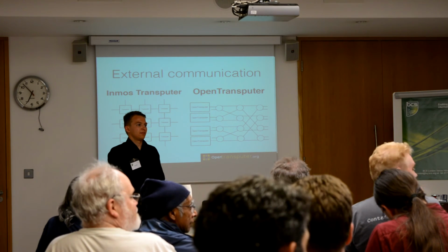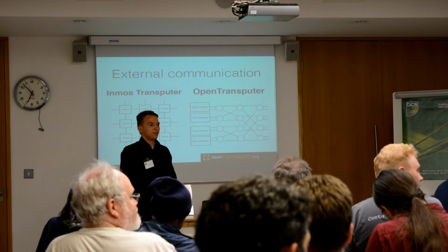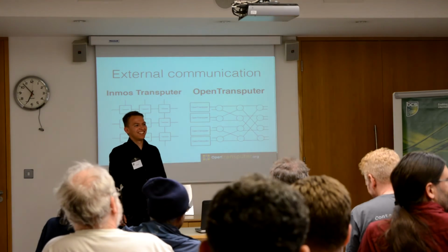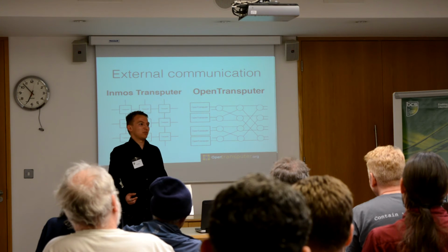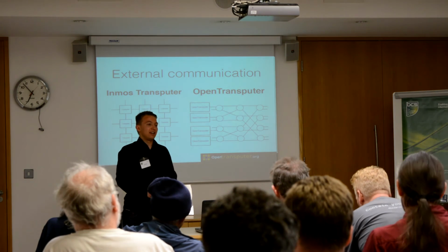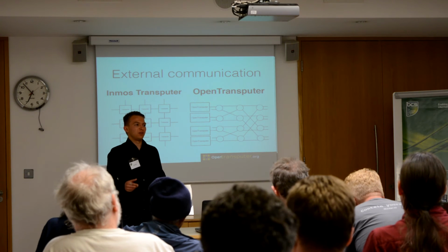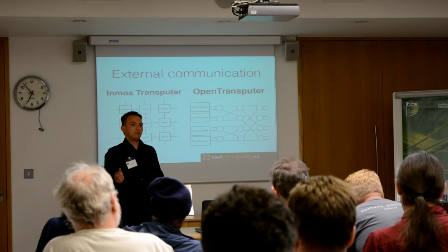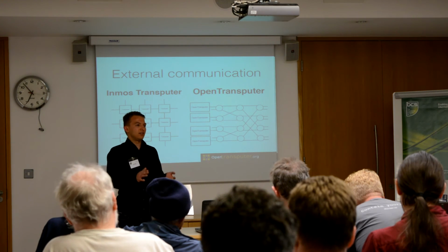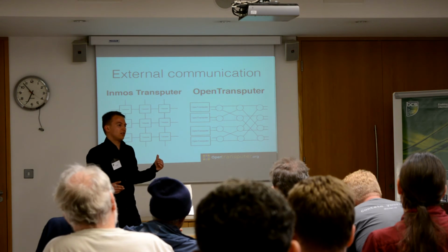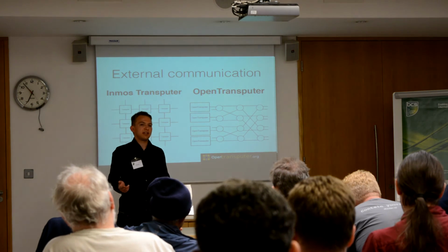Andy? So on that similar subject, have you seen the XMOS processor and how do you compare? Yeah. So I've actually used an XMOS processor as part of my degree at the University of Bristol, and the architectures are quite similar. The XMOS uses quite a few of the ideas that made the Transputer what it is. The main difference, I'd say, is the XMOS processor is a register architecture, whereas the Transputer and the OpenTransputer is a stack machine.